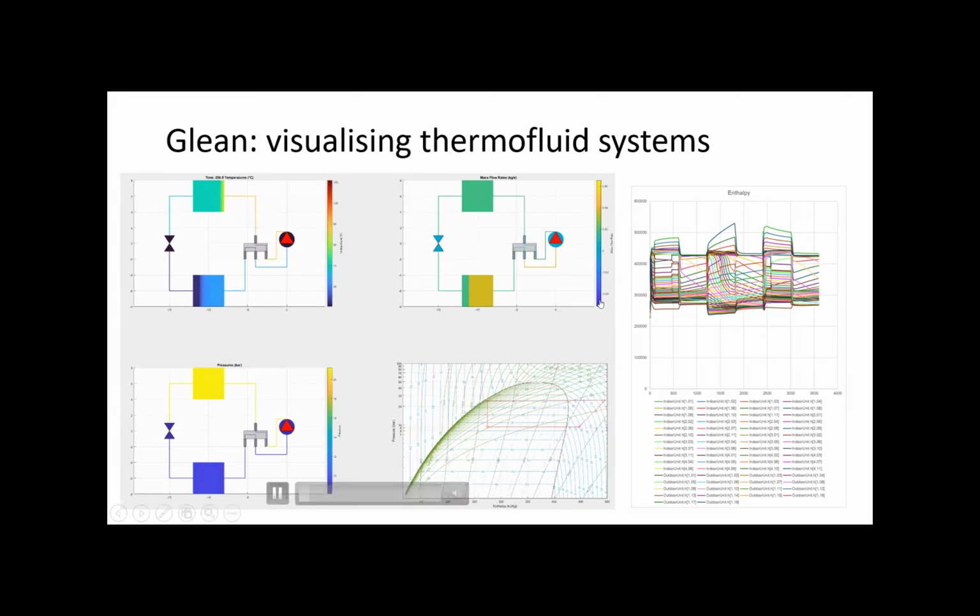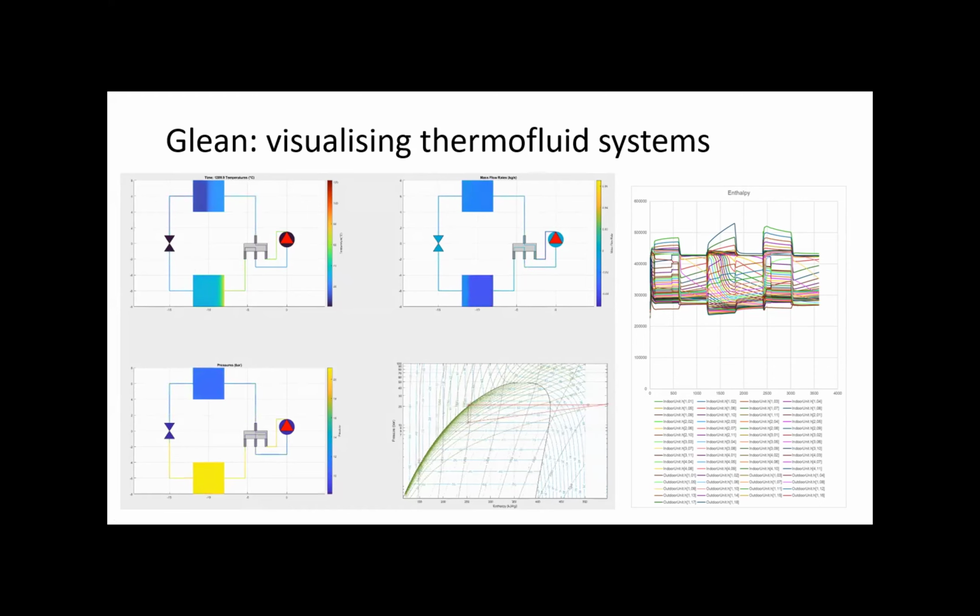And with a plot like this on the right side of the dynamics, you can actually get a much more visual understanding of how the system behaves, how much the length is inside the condenser that you're wasting, cooling and heating and so on, and what are the different flow rates in the system, the pressures and so on.